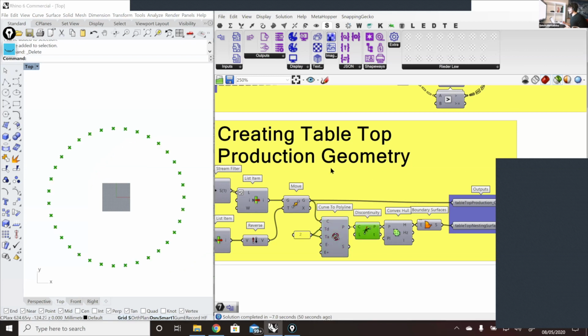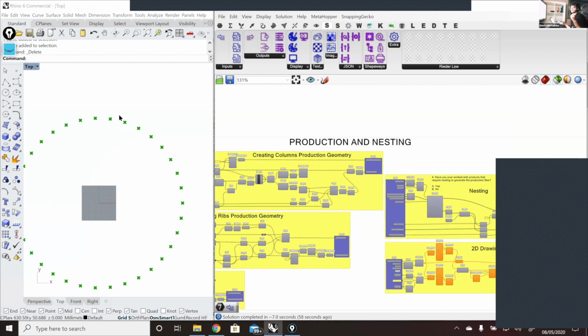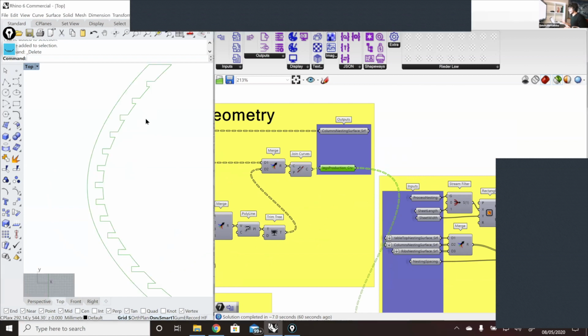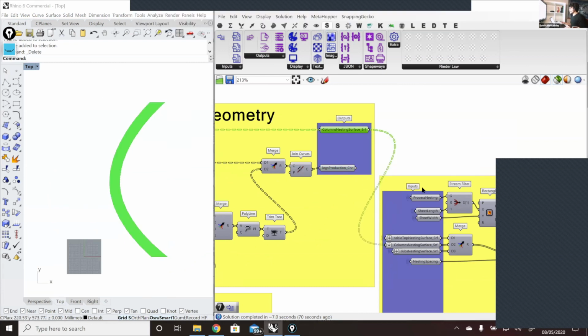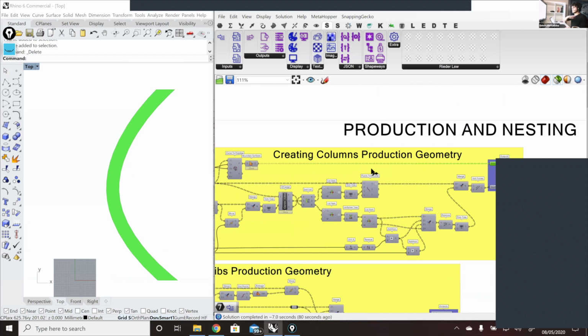So we have here the legs for production. You can see here how they look with all the notches, but all of these notches are not really necessary to be sent to the nesting, because of course we know that there is not a single thing that will fit inside here. Therefore, I create another version where you don't have that. You have it completely plain without any of those details, and you also make it a polyline, and you give it less resolution than what you would do with your final nest files. This is just used for nesting.